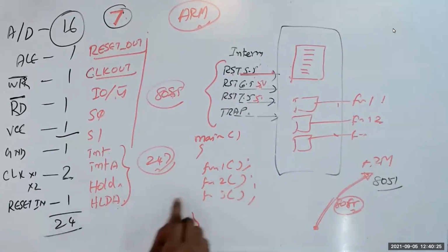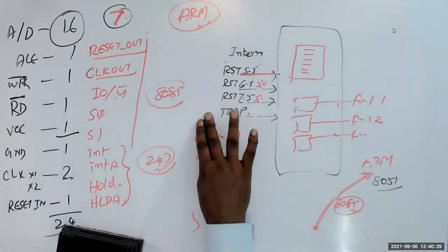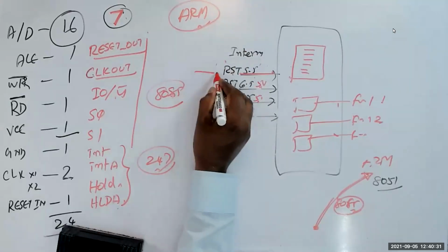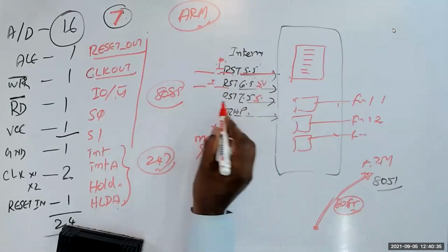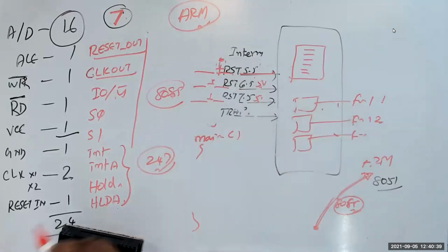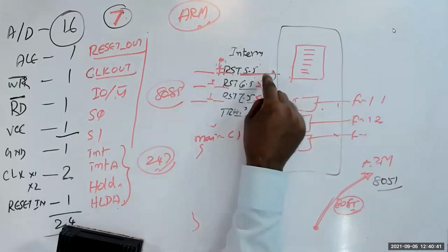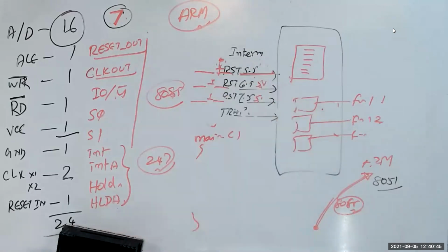But now I am calling these functions, instead of from a main function, through hardware. Let us assume that I have 3 switches. When I press the switch, it will go here. Understand one thing, that is called an interrupt. I execute the software through my hardware signal, without calling a function through your main function. That is a trick.